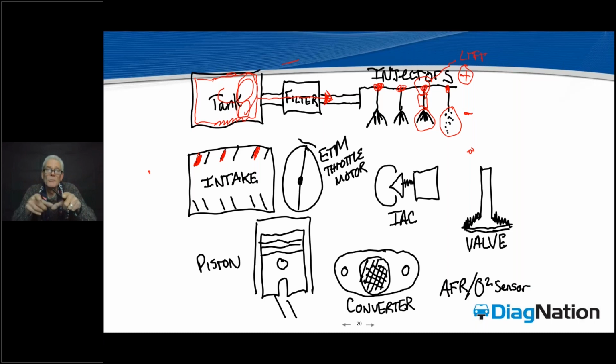Those of us that have looked with a borescope on car after car after car, you can see an almost Grand Canyon-like buildup of carbon. Looks like peaks and valleys all through the intake. And what the valleys are is simply where the main airflow charge is actually flowing. The carbon's going to build up around it.